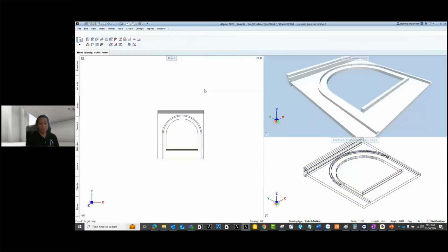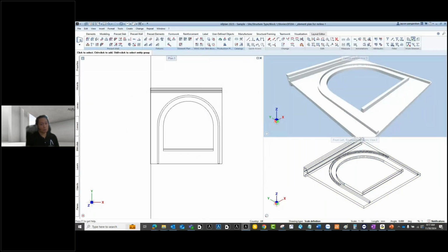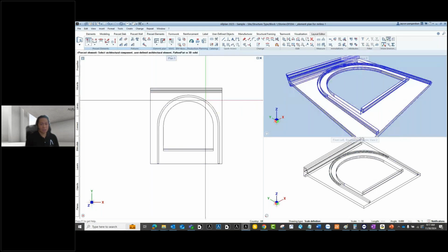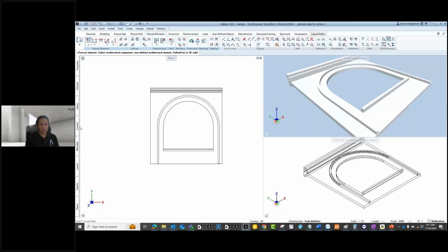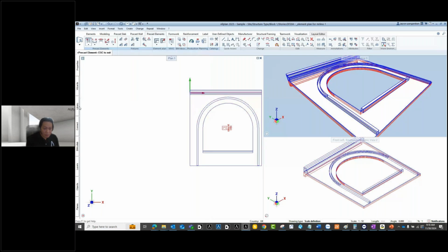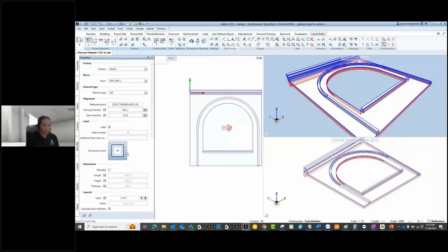Okay. So next is, of course, for precast elements, we just need to convert it. For cast in situ items, we just leave it as a 3D object. But for this case, we just convert this to precast. But yeah, it's reference property. So I just select this one. It's my precast. Let me just activate this one. Okay, just change the one. Yep, this one. All right.